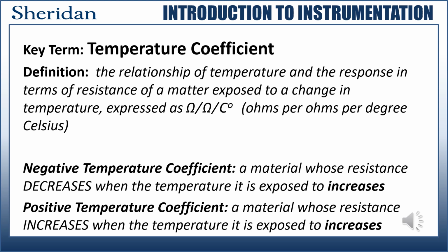One drawback, however, is a possible thermal runaway condition, which is possible in some lithium-based batteries or in some semiconductor materials. In these cases, the heat adds to the excitation, and the result is the internal heat cannot escape, and ultimately there's a failure. Positive temperature coefficient, or PTC, materials raise their resistance when the temperature rises, and decrease their resistance when the temperature lowers. Copper and other conductors behave in this manner.